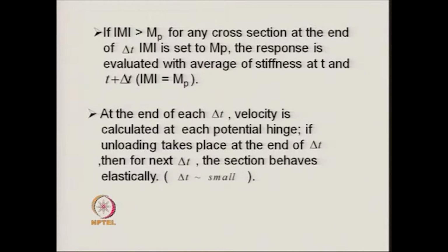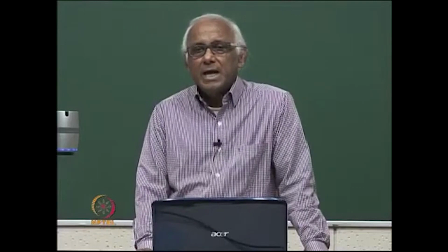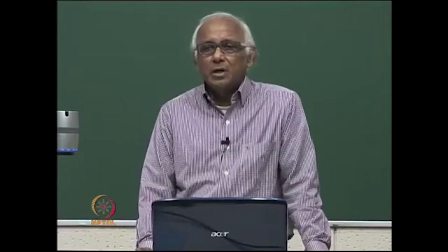One part of the loading takes the system to the state when it just reaches yield point, and then the other part of the loading in which the system behaves plastically, and the responses are calculated for these two parts separately and added together to get the final response.